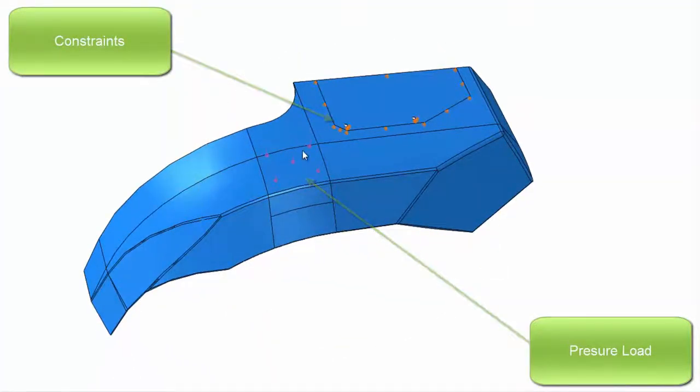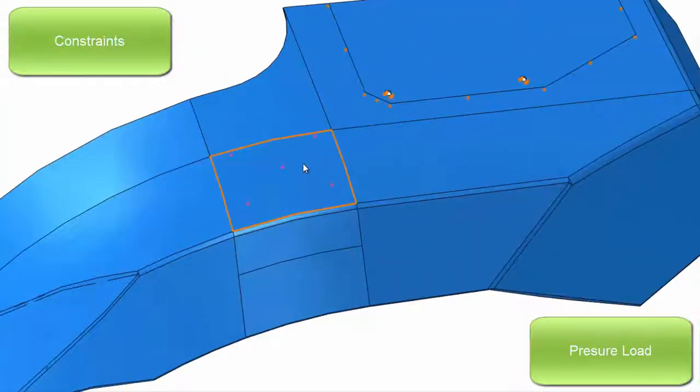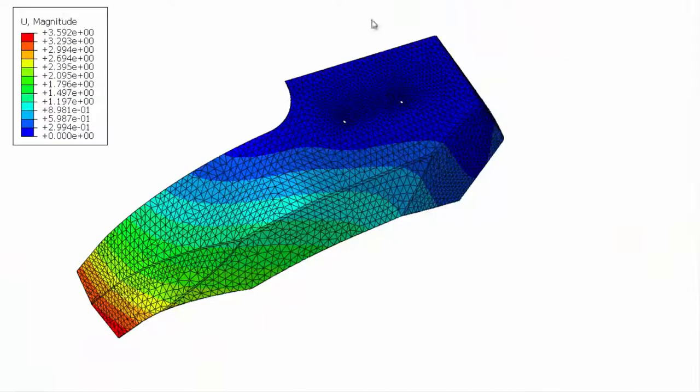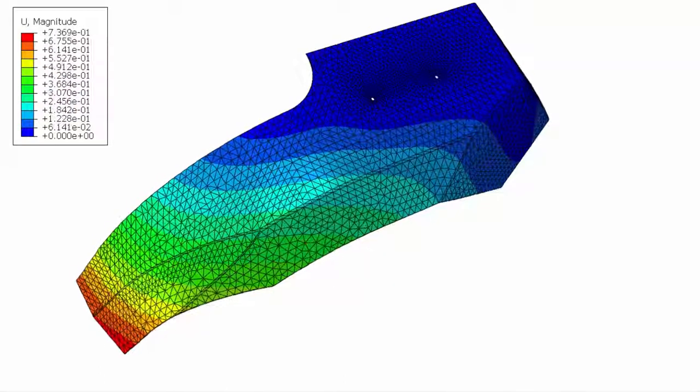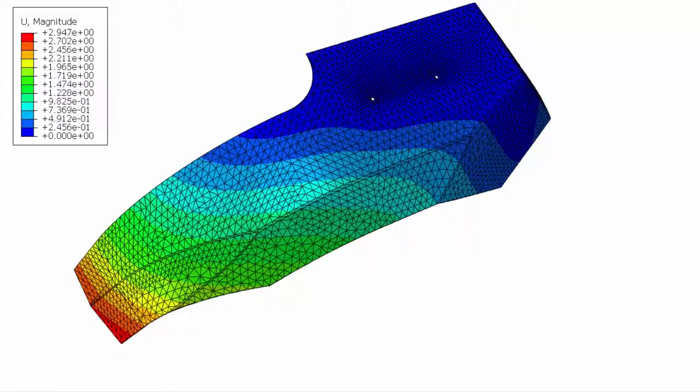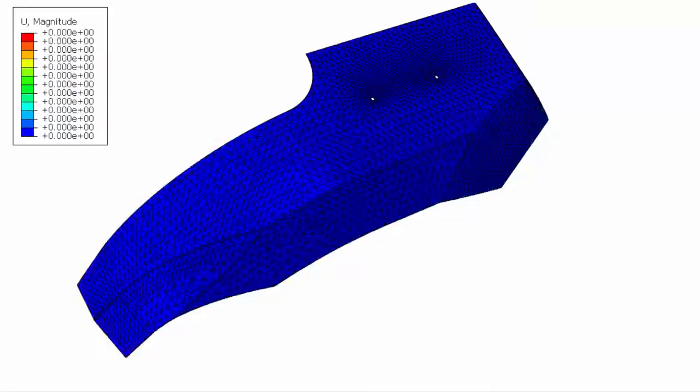Using as-manufactured properties within the structural simulation can only increase the accuracy of the structural simulation and help to identify potential areas of concern before the part is manufactured. Structural simulations have different requirements than those of the manufacturing simulation. Therefore, most structural models are oriented differently than those used for the manufacturing simulations and have a different mesh.